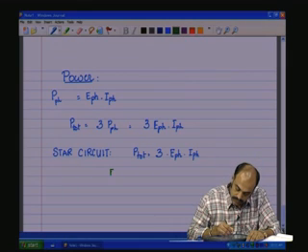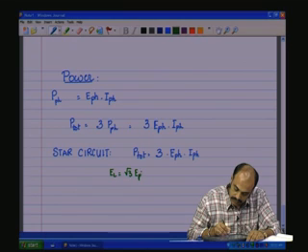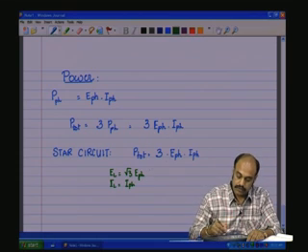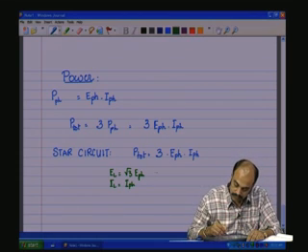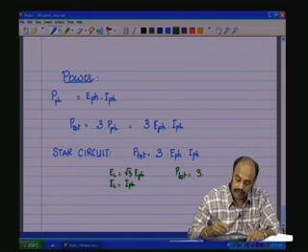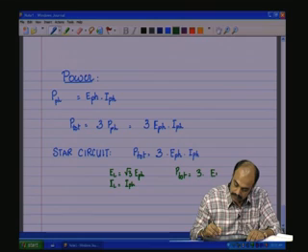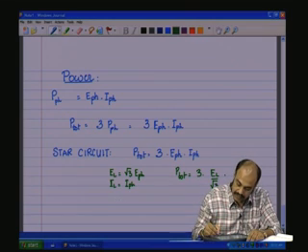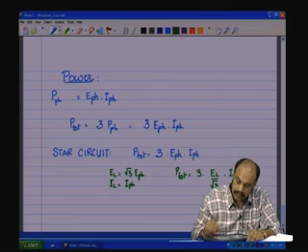We use E line equals root 3 E phase, I line is equal to I phase. So, substituting these here, you have P total is equal to 3 into E phase, which is EL by root 3, I phase is same as IL, therefore, we put it as IL.